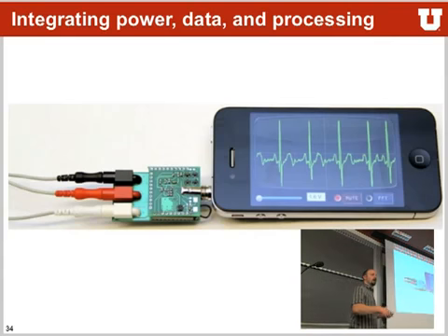The MSP430 was actually measuring these signals and transmitting them over the bus that we have over here, over the headset port, basically using audio signals. It was just beeping up and down and modulating the signals so you could actually get it through the headset port. An application over here was decoding all of this and showing you the data. So really this has all the elements that an embedded system has these days: communication, power, and some math, data input.